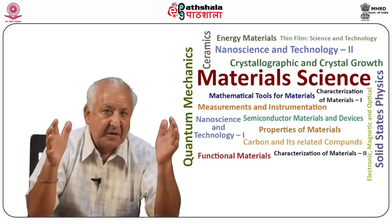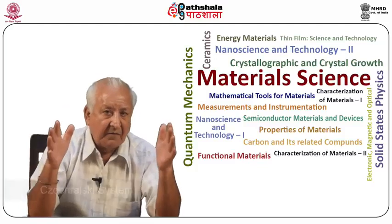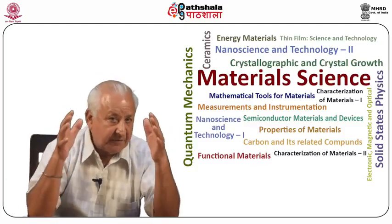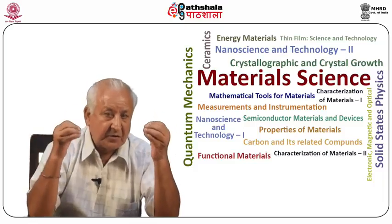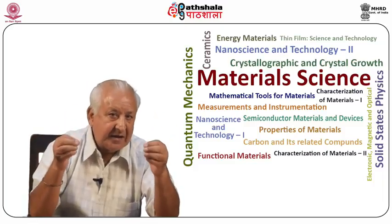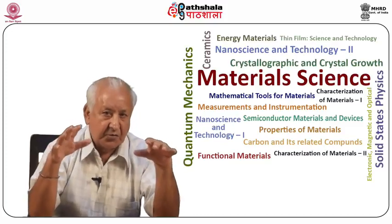The basic system is almost the same as that of the Czochralski system. However, the difference lies in the fact that in the Kyropoulos method, the seed is brought into contact with the melt as in the Czochralski method, but is not raised during growth.